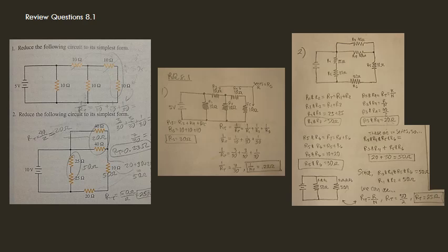So our resistance total, we can find out by using, since the circuit is now a purely parallel circuit, the formula for resistance for a parallel circuit, which is our reciprocal formula. So we can say 1 over RT equals 1 over R1 plus 1 over R2 plus 1 over R3. In this case being 1 over 10 plus 1 over 10 plus 1 over 30.